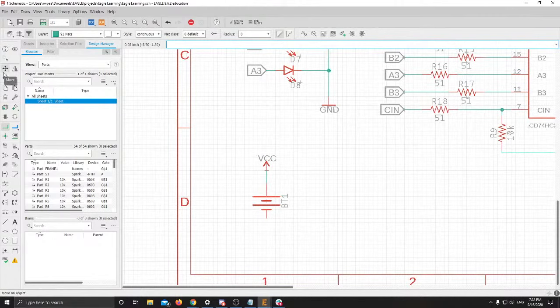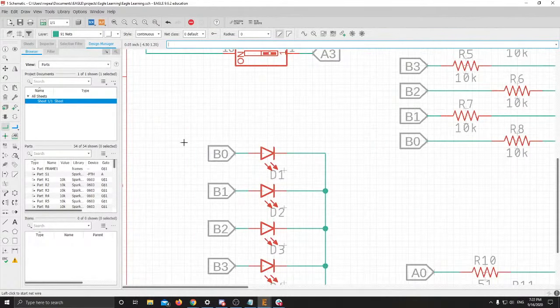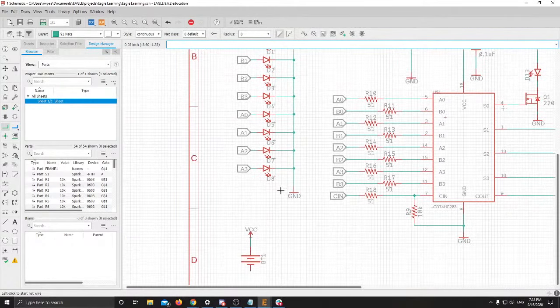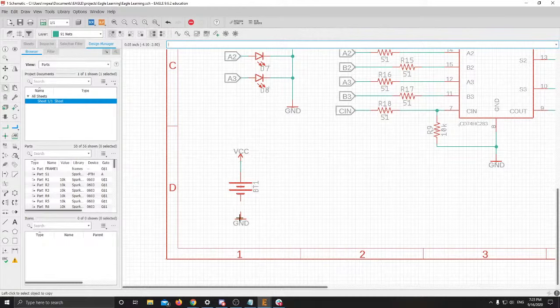But if you have the same voltage and different VCC symbols, it's not going to figure out how to connect them. And that's where, personally, I prefer to just name one of my nets, like VCC 5 volts, instead of using the symbols. But that can be a little bit harder for other people to follow. Either approach is valid. So I'm going to go ahead and make that connection, and then we'll add our connectors.